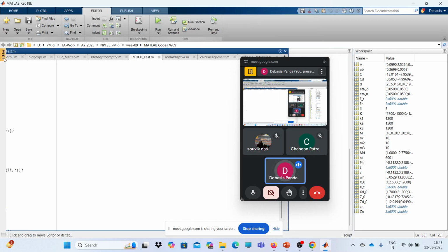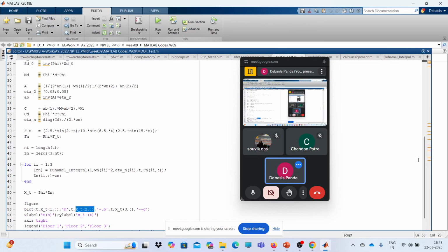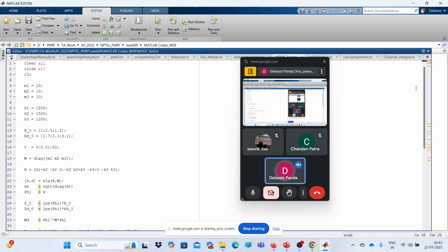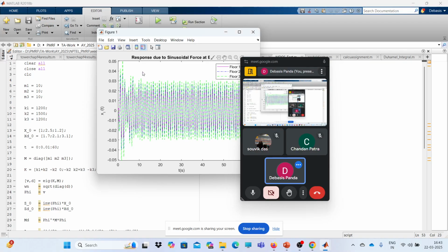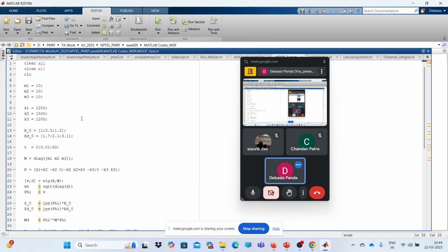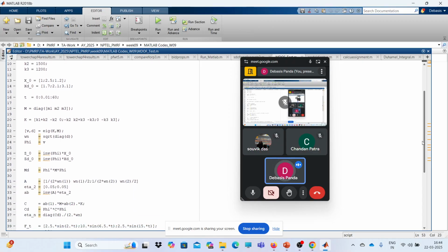Now once we have all these things, we can calculate the responses. With 5% damping, we have the maximum response corresponding to 0.4 or 0.3 in the steady state part. If we look at the steady state part, we have the peak response of 0.3. Now if we change that damping property, let's see what happens.